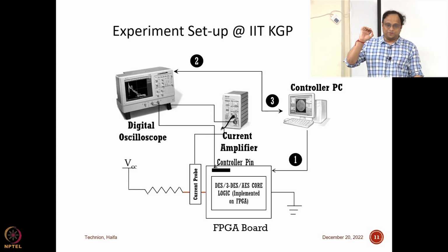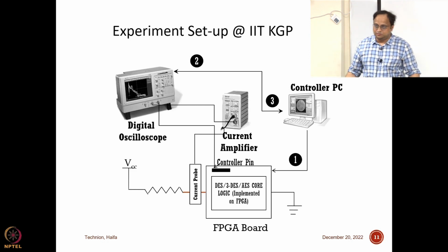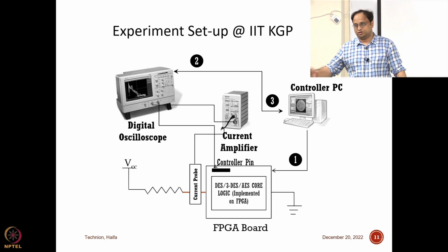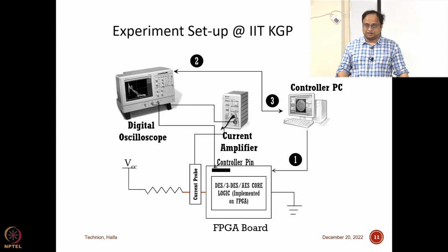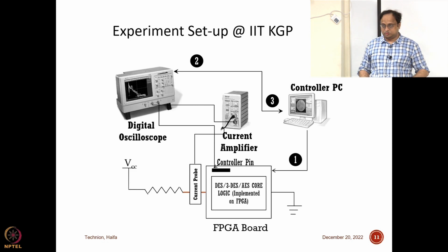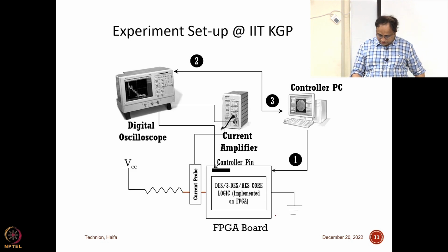Okay, so now if there is, for example, some kind of crypto engine running over there, and when it is performing its operation, you are curious to know what the power consumption is during that computation. This is a very classic setup that you can see here, which we have in our lab. So we have an oscilloscope, we have a PC which controls and synchronizes the computation and the communications, and there is a device under test.